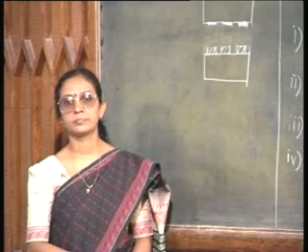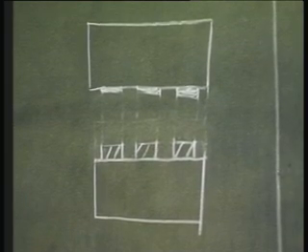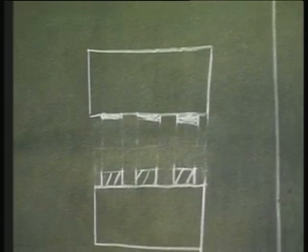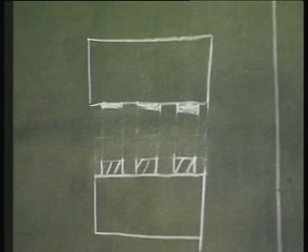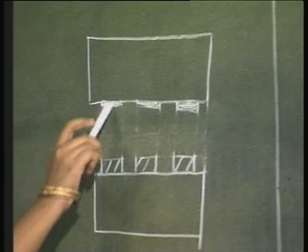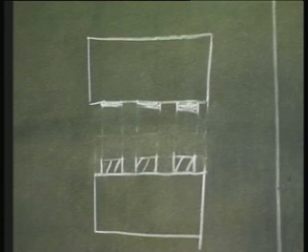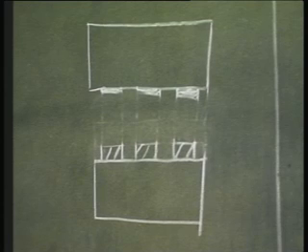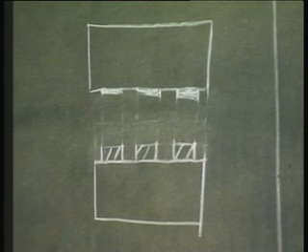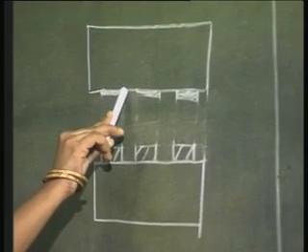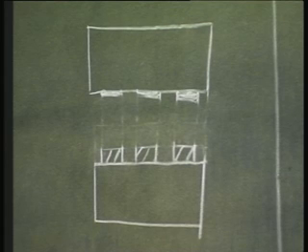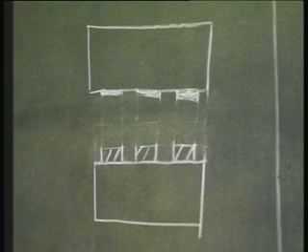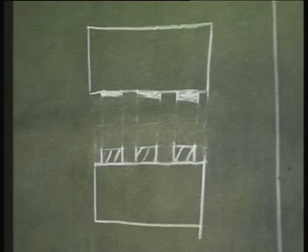What do you see here? Compare the pattern on the mask with the pattern on the oxide. The opaque regions in the mask, corresponding to that I have oxide sitting on the wafer. The transparent regions in the mask, corresponding to that I have no oxide. So, now if I dope the semiconductor, which are the regions where the dopant will get incorporated? The regions corresponding to the transparent portions of the mask. In other words, these windows are the windows I have opened in the oxide. The pattern on the semiconductor has a 1:1 correspondence to the mask pattern.